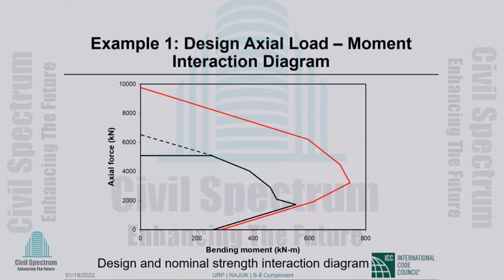Now let me continue a little bit. Let us say in that 12-inch by 12-inch column, instead of four bars, you had six bars. So there are two additional bars, and somehow you place the additional bar not in the middle. If it were in the middle, you wouldn't go beyond the 6-inch clear spacing.